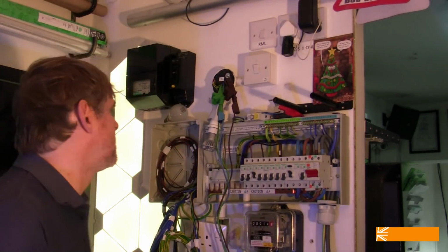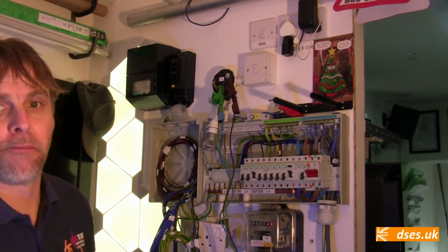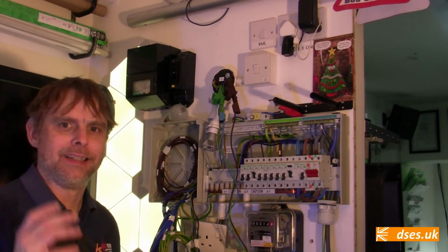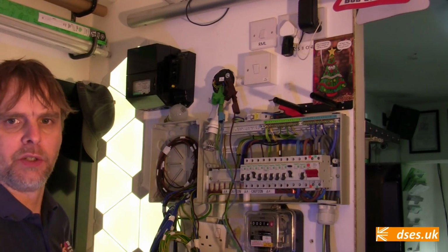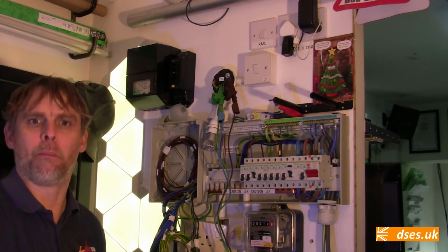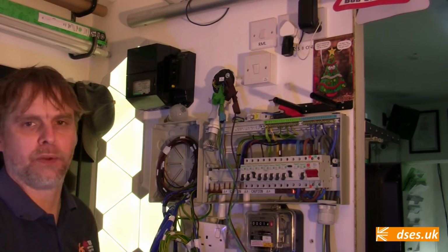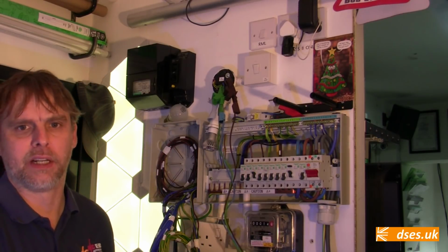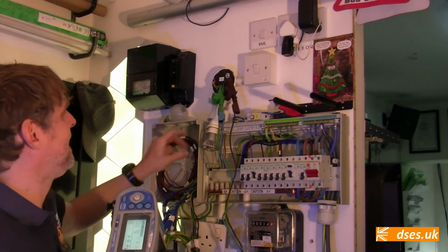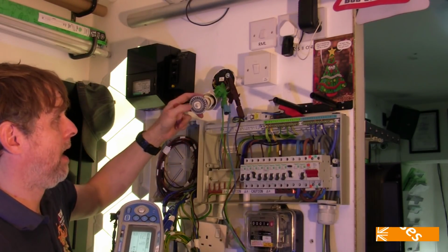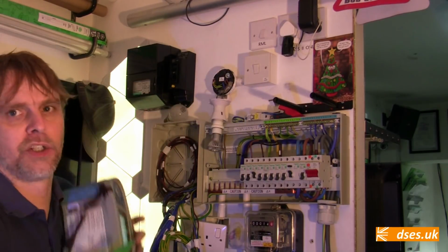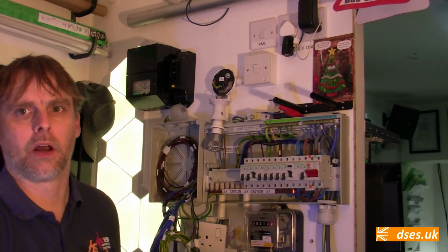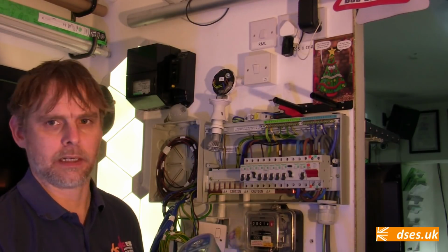So what the Mary Poppins is going on with this thing then? Well, to be honest, I don't know. My assumption is that these different testers with their different chipsets and probe impedances are each squashing this induced voltage as they try to read it, and as it has no real meat behind it, you're getting some differences in readings. You'll notice also that merely connecting any of these voltmeters extinguishes the light. If I disconnect this, it comes back on. So just connecting a voltmeter to it causes the light to stop glowing, which is interesting.